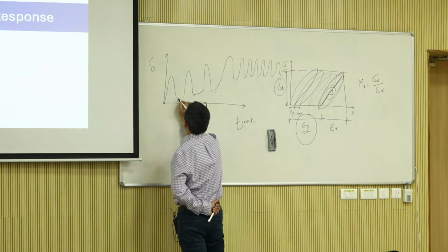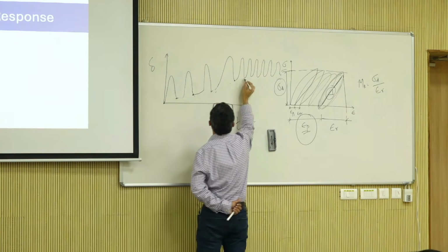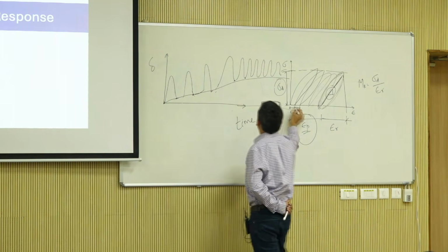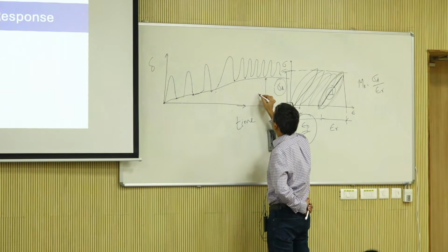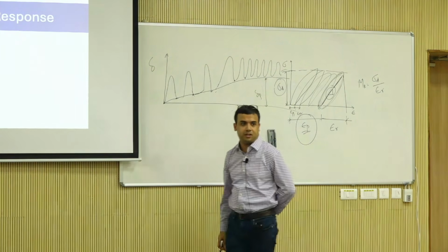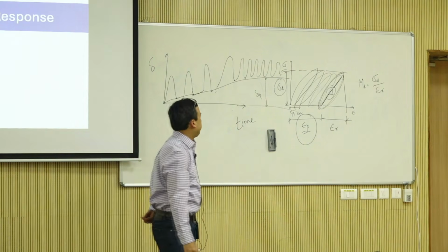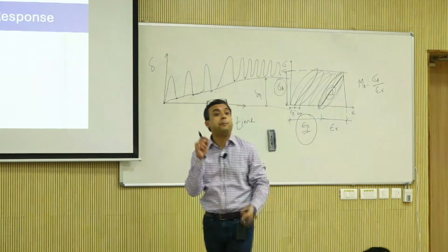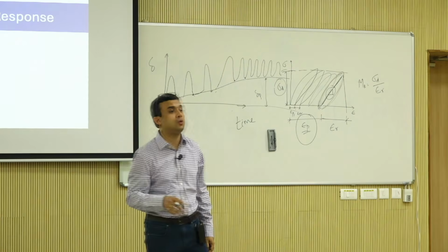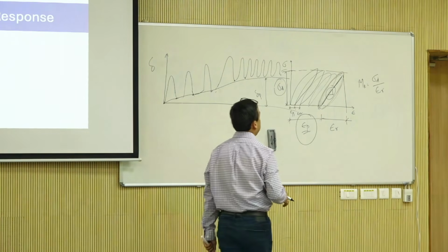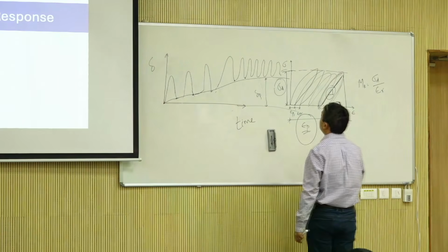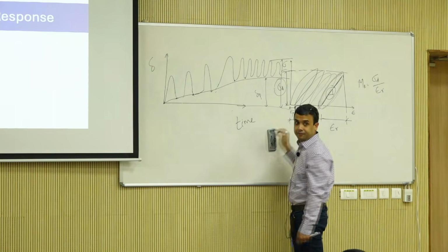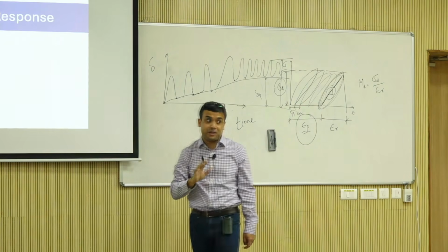Now if you take the bottom points of all of these graphs and you draw this, that becomes your delta P or permanent deformation, right? And everything on top is the recoverable part. So if you put an LVDT on your specimen, what are you going to measure? Which deflection? The vertical, which is the total, right? You're going to measure the total.